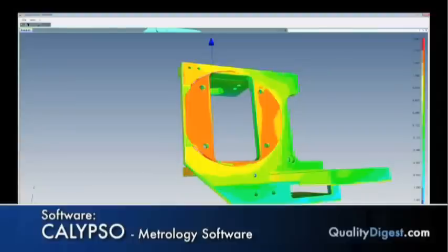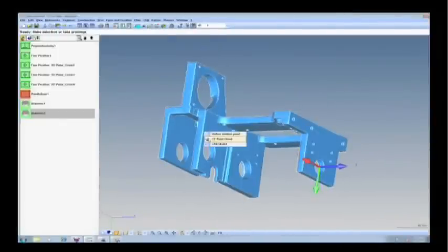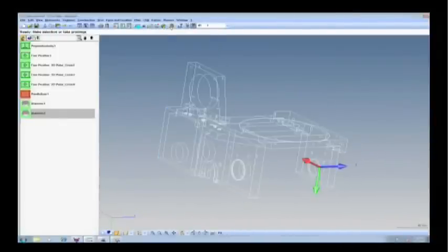So now we're overlaying that data on the CAD file, and very quickly finding out how the part looks overall, what the deviations to nominal geometry are. If I click at certain locations, it'll tell me what the deviations to CAD are at those locations. So let's quickly run some of the characteristics that Scott built.